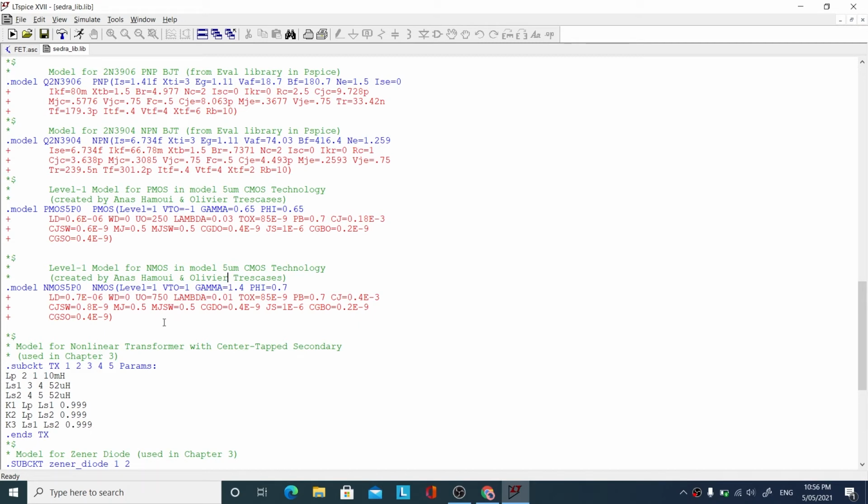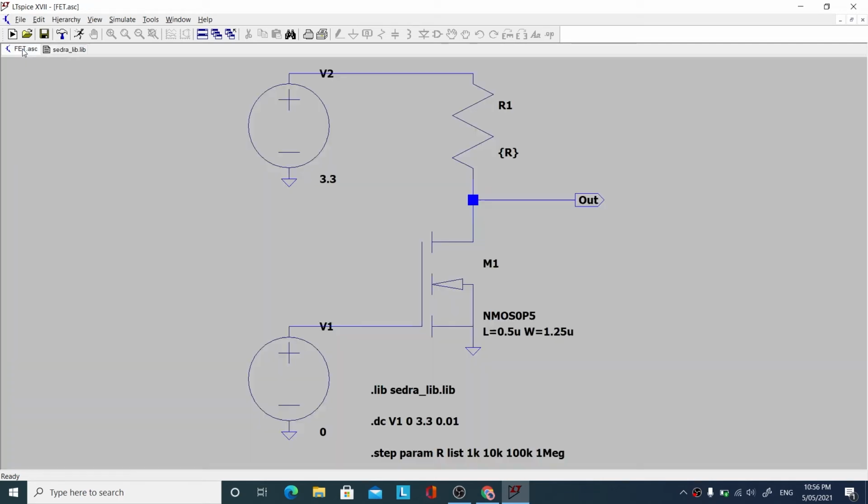If you want to understand how to model FETs and how SPICE works in general, then there are books that dive into that for you. All we need to know is that this is a fairly typical NMOS FET that you at least used to find in CMOS technologies. 5 micrometers is considered quite large by today's standards. Nevertheless, the fundamentals never change, and it's more than good enough for what we want to do. If we go back here, we want to run this circuit to see what the output looks like as we vary the input. So we just click on the running man here